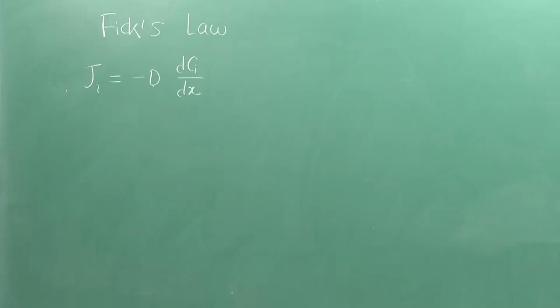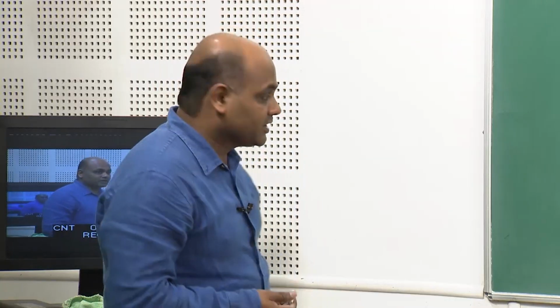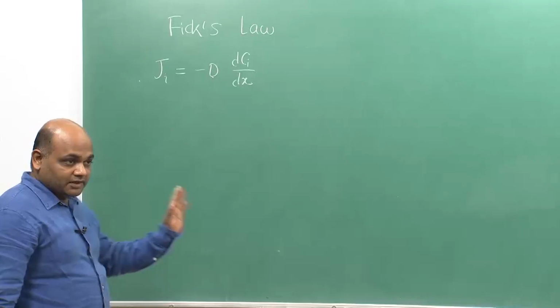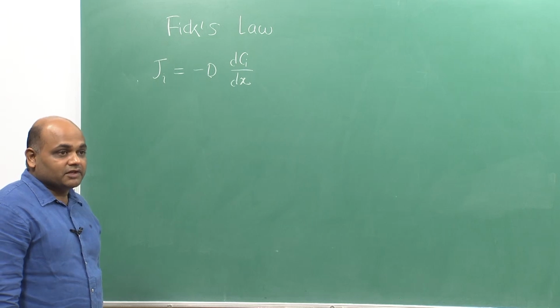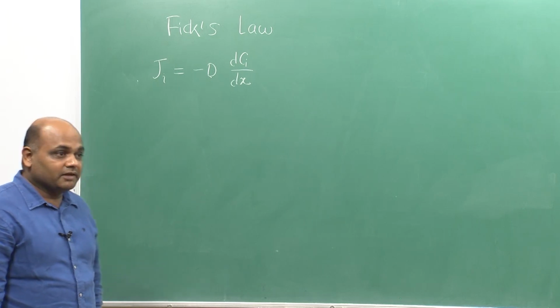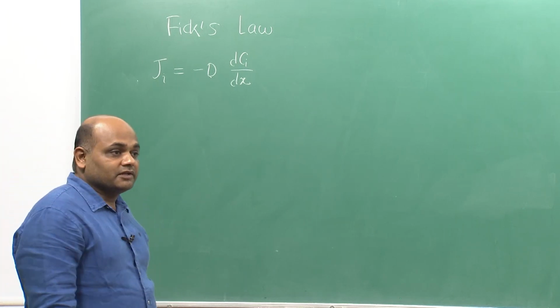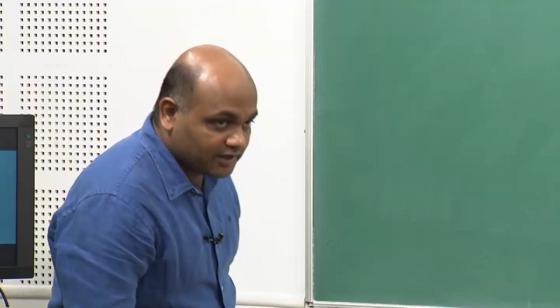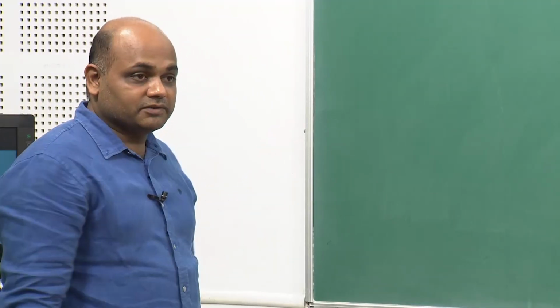So, this flux based upon the concentration gradient of the component is also referred to as Fickian flux. What can be other reasons for getting a flux? If there is an external driving force, you might also get a net velocity of the components, or the net velocity of a concentration plane because of the external driving force, and it will be also added to the flux term.